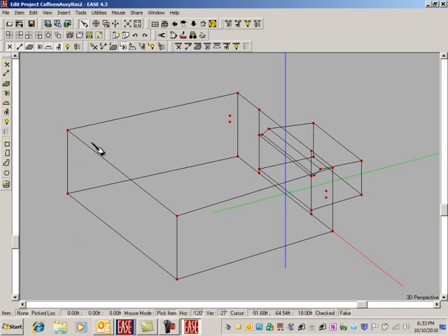Say OK. And then now I've got the other corner. Now I can duplicate this guy down 3 feet, just like I did before. It remembered that because keep is checked. Say OK. Now I have the vertices for my glass. I'm going to add a face between these vertices. So I'm going to start by adding a face. I'll just make it an inside face. I'm going to modify it here some, like this. This is my glass now. There, we'll create it.